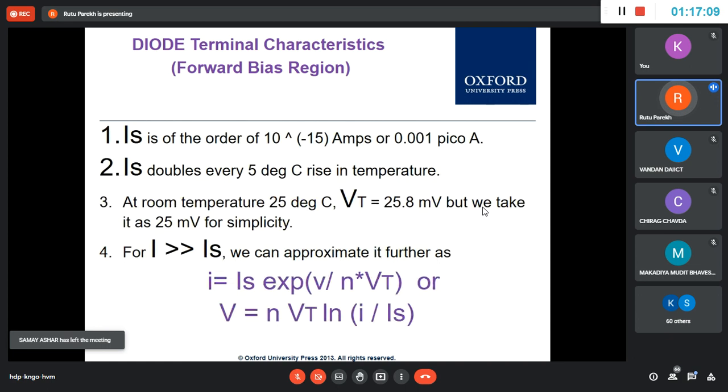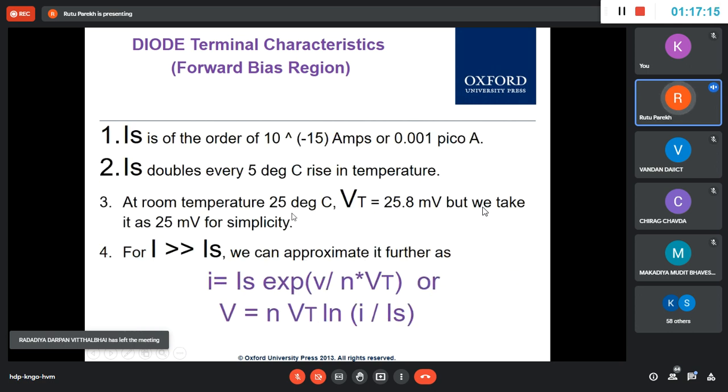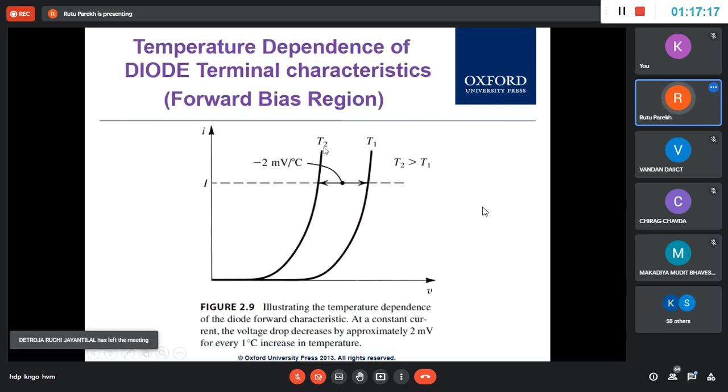That's how the temperature sensor works. The current is a function of temperature, and from measuring different currents you can know the temperature. That's how we already make sensors using only this criterion. Because with the change in temperature, for a constant voltage, I is changing. If you measure I, you will get temperature, and that's your temperature sensor.